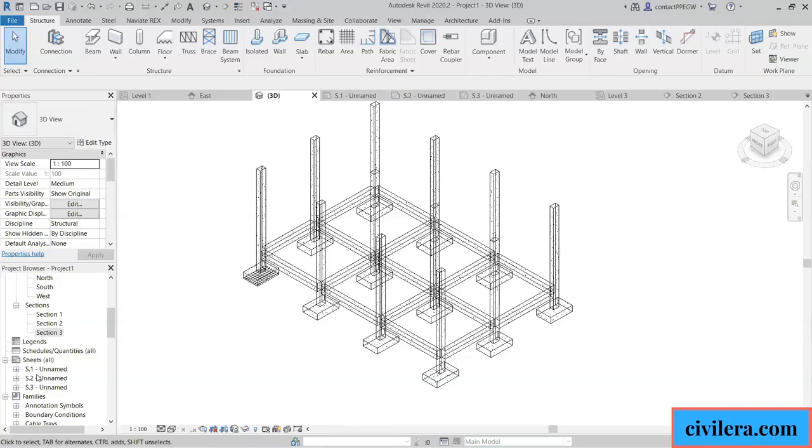And every drawing, if you have 100 drawings in a project, everything is in one file. In AutoCAD, you cannot save every drawing in one file because it gets heavy and then you will have all kind of issues. Here, if you have 100 drawings in a project, every 100 drawings will be in one single file. So your control or ability to control the drawing, or to save the drawing, or to carry the drawing, everything will be easy. You need not struggle to find the latest drawing and things like that.